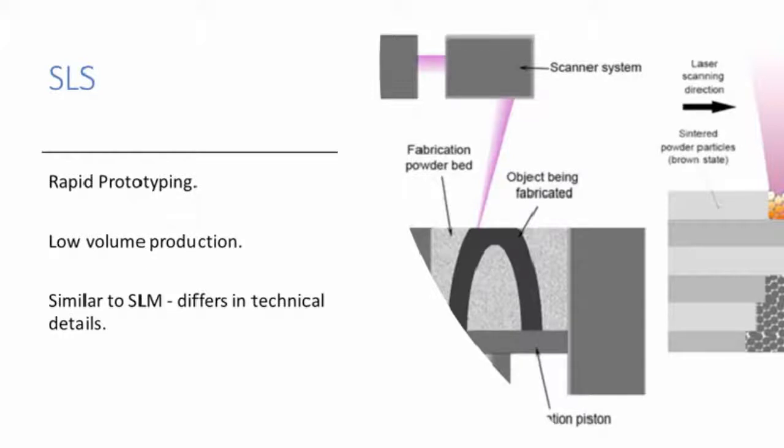In contrast with some other additive manufacturing processes, such as FDM, which requires special support structures to fabricate overhanging designs, SLS does not need a separate feeder for support material, because the part being constructed is surrounded by unsintered powder at all times. This allows for the construction of previously impossible geometries. Because SLS can produce parts made from a wide variety of materials, such as plastics, glass, ceramics or metals, it is quickly becoming a popular process for creating prototypes and even final products.